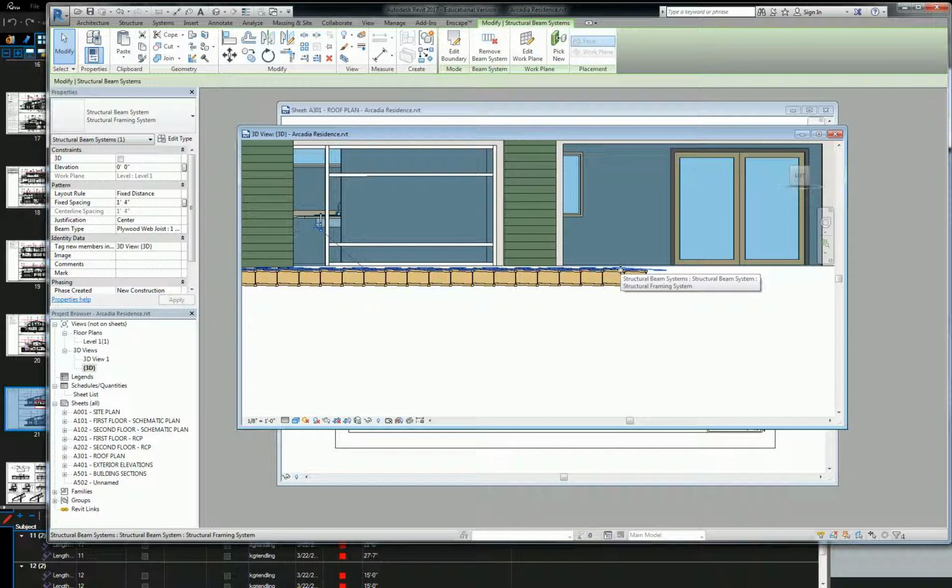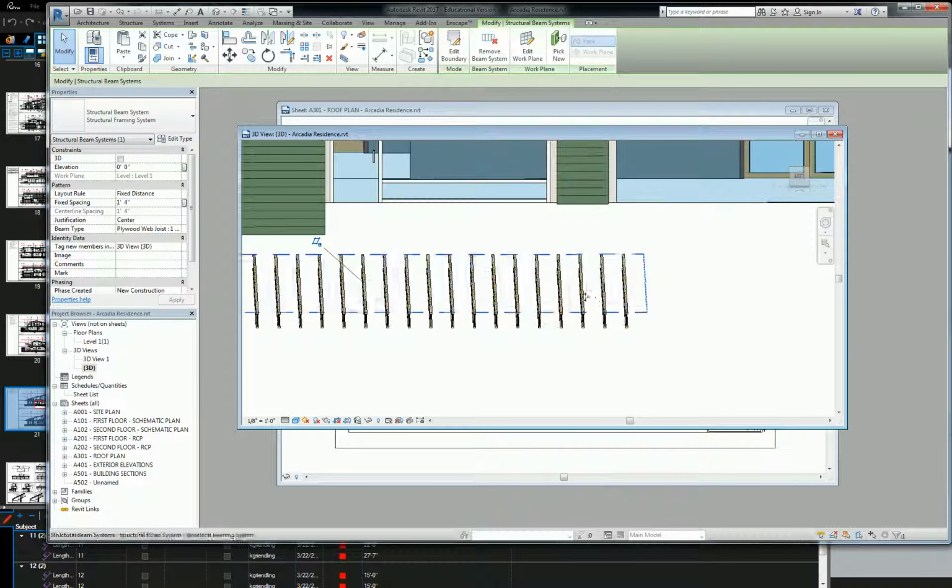If you have a wide flange in the field of architecture and structural design, when you're drawing your plans, the top of steel elevation is the one that gets called out. Everything is measured to your top of steel, or top of structure for wood. So that's why these things are extending downward.